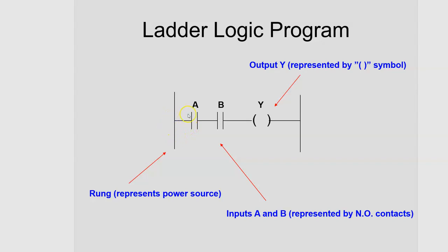But you can think about this A and B, what look like contacts. They're in series, so that represents AND logic. This is an AND circuit. The output over here can only go true, or turn on, or be activated if this contact is closed and this contact is closed. So as I said before, this represents AND logic, but realize this is not a wired diagram. This is all basically virtual. This is a program. And so you'll actually have these instructions available to you.